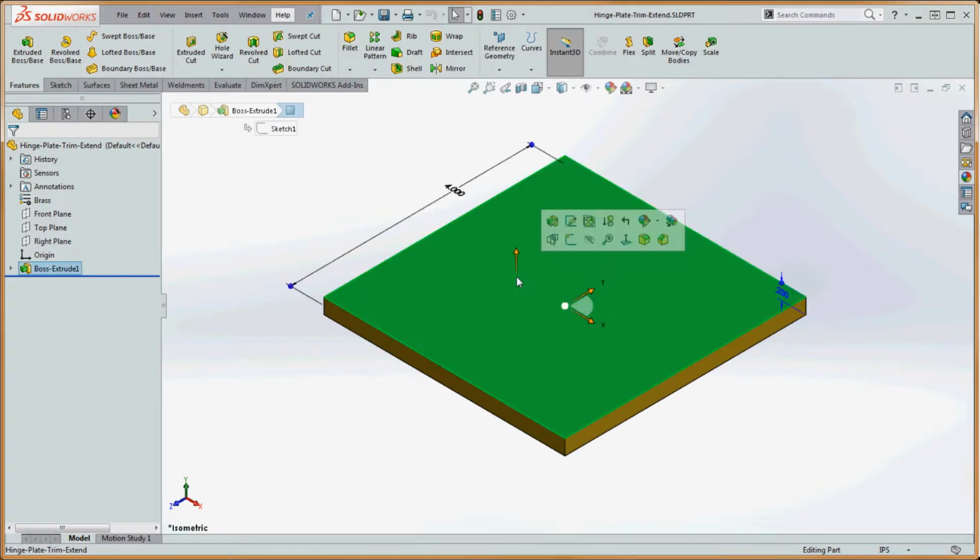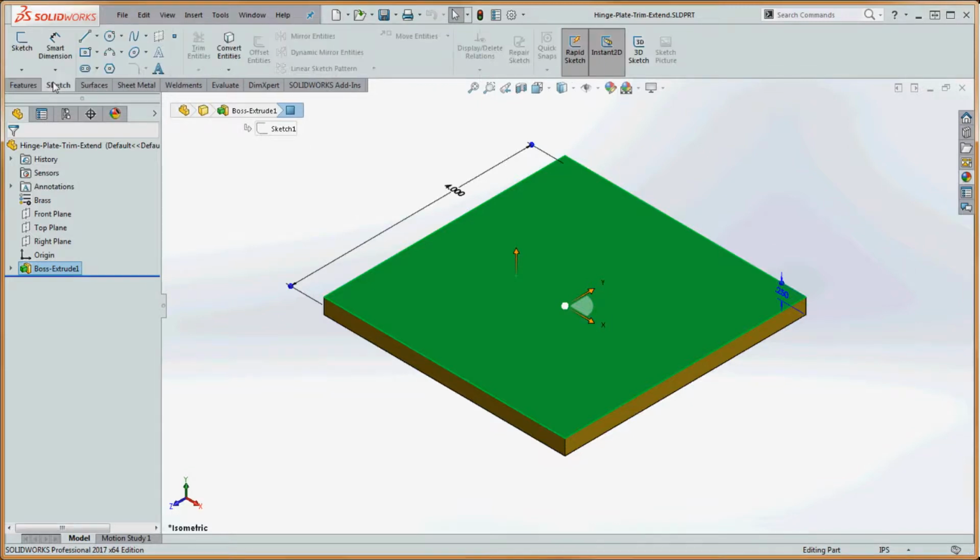So we're going to go ahead and click on the surface, and open that surface for sketching. So what you want to do is click on the surface as opposed to the primary planes that we have in here. Now that we have an object in here, we can use some of the surfaces associated with that object. So if we click on that, go to the Sketch tab, we're going to go ahead and sketch out some elements in there.